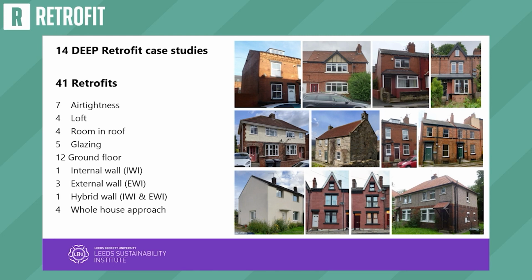14 homes, we undertook step-by-step retrofits. Lots of different retrofits going on in these homes. Not every home had the same retrofit, but they were all solid-walled homes. We wanted to identify the disaggregated impact that each of the individual measures had in terms of energy performance and thermal heat loss reductions, as well as moisture risks. So when you do change the building fabric, you change the building physics, you change the way heat moves, and that heat influences moisture. So that's important too.